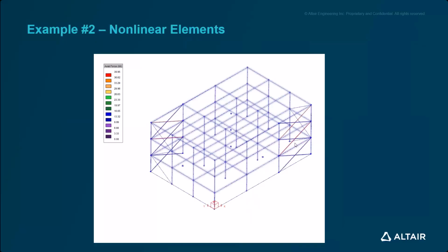The next exercise we're going to look at is using nonlinear elements. There's a variety of nonlinear elements in S-frame. I'm not going to touch on all of them. The one we're talking about today is tension-only members, and I think they're probably the most widely used in S-frame. We have compression-only supports. We have tension-only members. We have hook gap elements that we'll look at later. Cables. They can all behave nonlinearly, and their behavior might vary on the application.